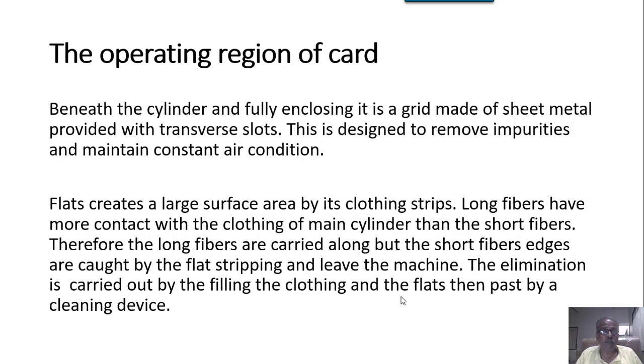Release is important for delivery from one rotating roller to the other rotating roller. So this is controlled indirectly by the air currents which are going around each of these rotating parts. So in a controlled way, airflow is required to be there in this machine. In the case of the blowroom also, as I have stated. So that plays a very important role.